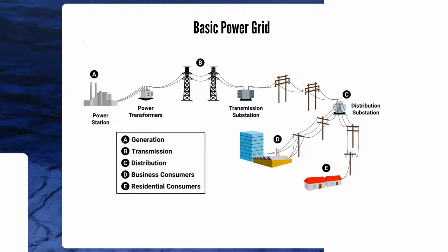But for the small conductors, it costs less, it's easier to handle, but it generates more heat. So, in transmission, really, the goal is to reduce current, to reduce the losses, and this is done by increasing the voltage.